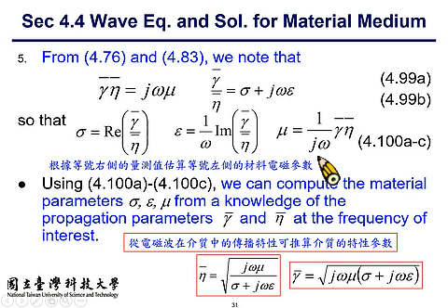which is controlled by your signal generator. So once you perform the measurement, you use the result to derive eta and gamma. Then you can use eta, gamma, and omega to estimate sigma, epsilon, and mu of the material. All right. So in practice, the EM property of the material is estimated using measurement results. They are not a given. All right.